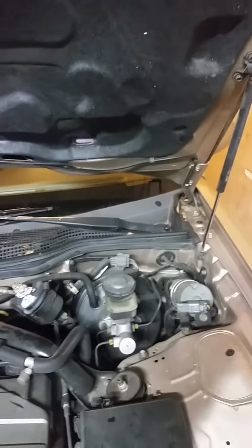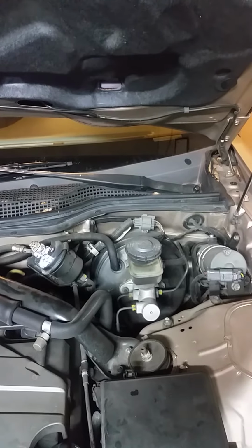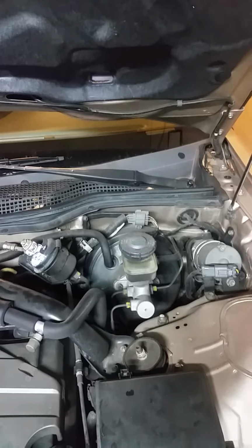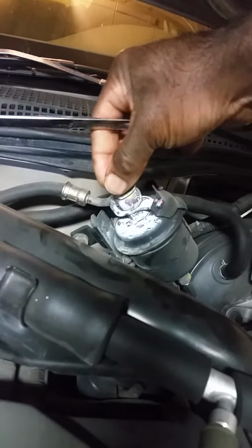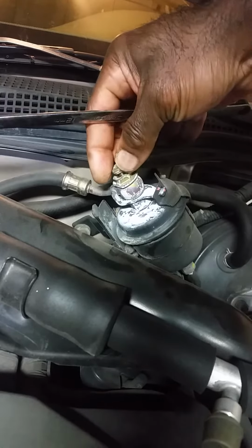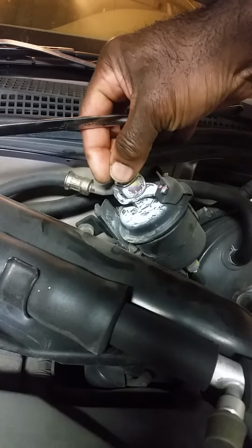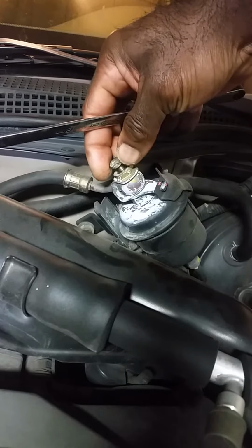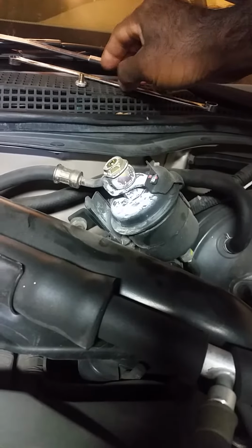One of the first things I should do here is disconnect the battery. But see, what I need to do is, okay, so I don't have any fuel squirting out, and I do want to put my fuel pressure gauge here. Let me go get that and pause here and come back.